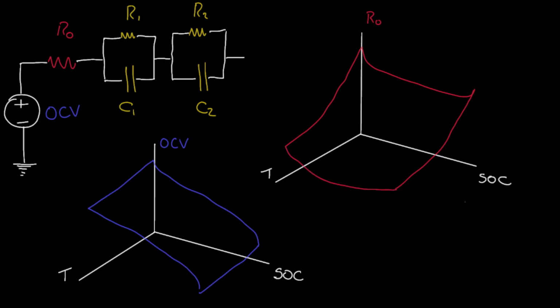Let's start with the basics. The battery pack is comprised of individual cells of a certain type and from a given cell supplier, with a unique electrothermal response, which depends on its materials and electrochemistry. These physical fingerprints are incorporated into the cell block as parameters of its equivalent circuit. Sometimes we refer to this as ECM, equivalent circuit model. Maybe you're already familiar with this concept.